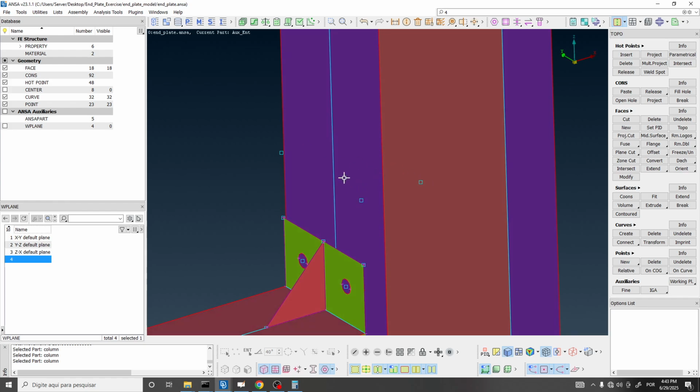I defined 3 points that defines a plane, right? With 3 points, we can define a plane. I'm going to use a tool here that is inside the faces group. Let me see. Plane cut. Yeah, I guess it's the plane cut. Yep. The plane cut tool inside the faces group. Left click here. If you don't see it, you can check other options here. Left click on plane cut, left and hold, and then